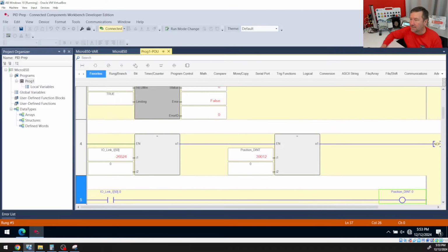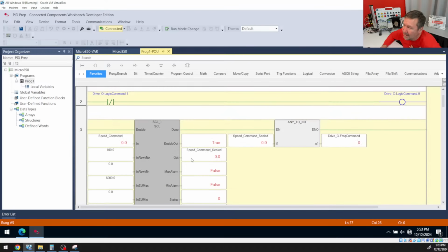And so what I want us to do is walk through this in structured text so that you can start seeing, one, how all three languages have advantages. And this one really is the clear one because even here we had the STL, we had to do the any2 int. We're going to do a lot of these any2s and we're going to have a lot of intermediate numbers in here. And if we just write this out in structured text, life's going to be easier. So let's hit disconnect.